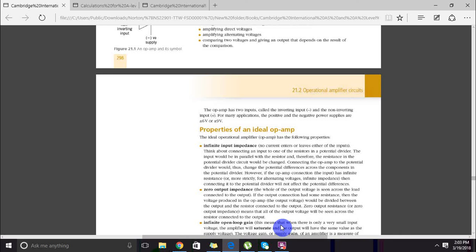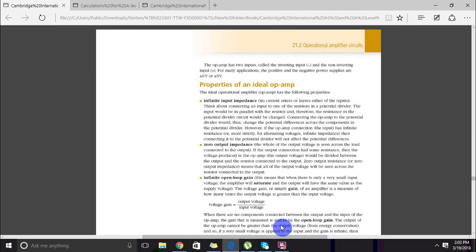Moving onwards to the third one. This is about something called open loop gain. So what is that? That's basically the ratio of the output voltage and the input voltage. You might be wondering, don't we have two input voltages? So how does that work? No problem, and this is actually really related to why we call the inputs one of them positive and the other negative, even though they're both receiving the same polarity of voltage. That's all going to make sense.